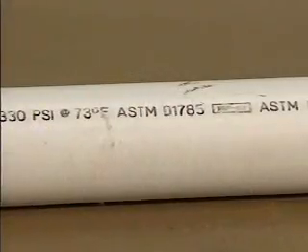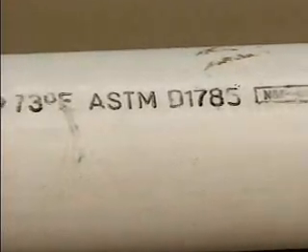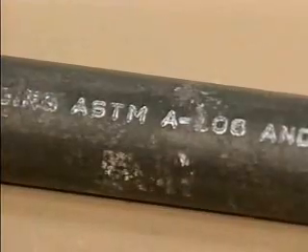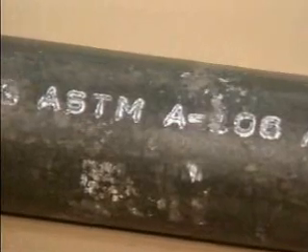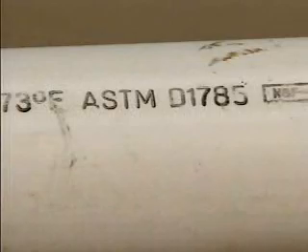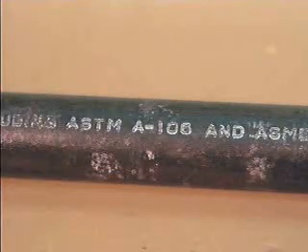Under the ASTM system, pipes and fittings are printed or stamped with a series of letters and numbers called an identification number. Metal that contains iron, or ferrous metal, has an ASTM identification number beginning with the letter A. A non-ferrous metal identification number begins with the letter B. An ASTM identification number for PVC pipe typically begins with the letter D. A number, usually 3 digits, appears after the first letter. This number identifies the specific properties of the metal.